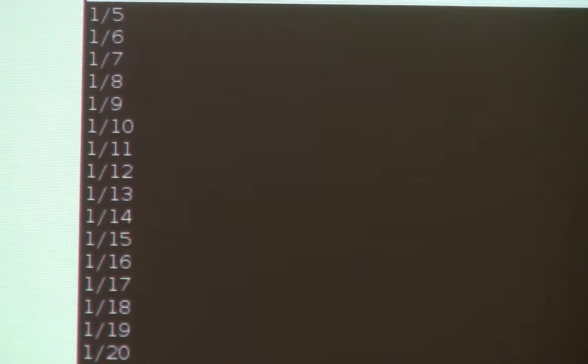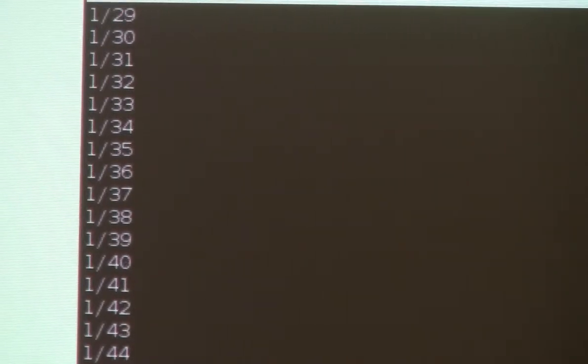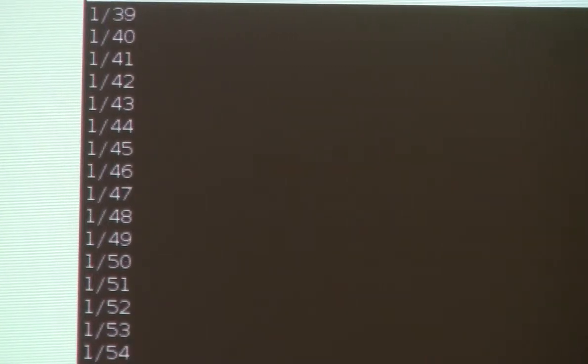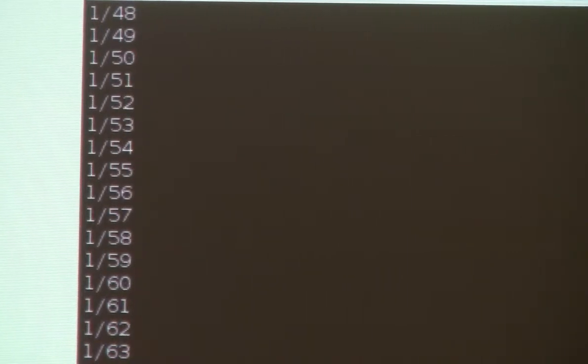So here it is, the check. So we've got robust communications of all characters, including hex-on and hex-off characters. If you want to communicate binary data between the two machines, you've got to make sure that you can transmit 0 and 255, some of these special cases. There are protocols where you can only use the 7-bit ASCII, normal ASCII things. But what I've been doing tonight, I can send all 256 combinations.